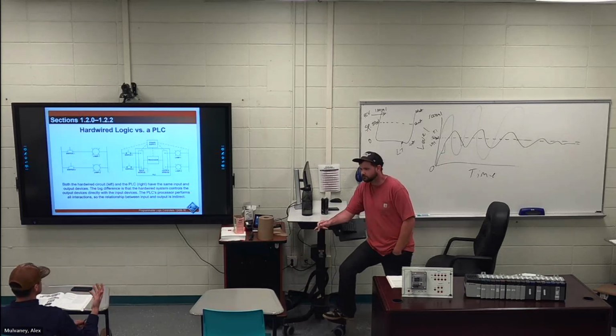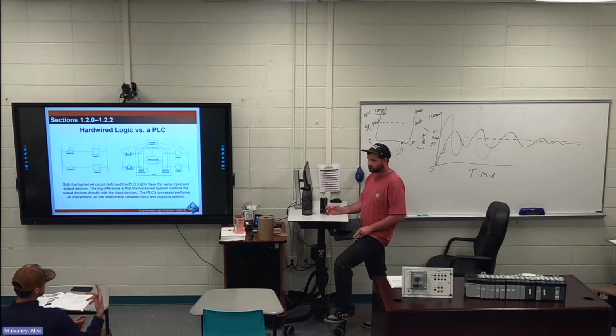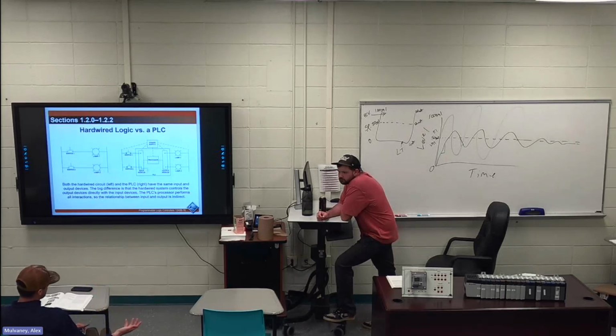So when I was troubleshooting it and I told him to send it a signal to open, I took the hose off the solenoid valve to see how much air was coming out. It popped open, air came out, and then after a couple seconds it stopped. Shouldn't be doing that, right? It should stay open. Solenoid valve. Yeah, solenoid valve should stay open.